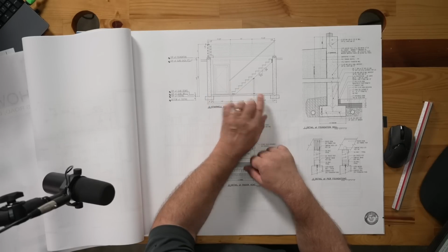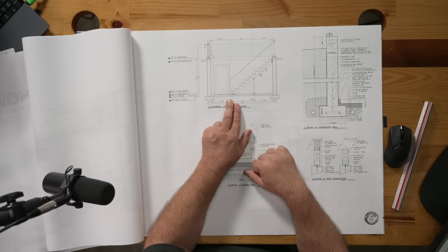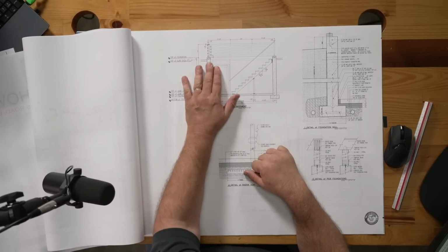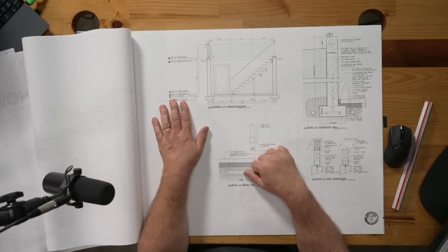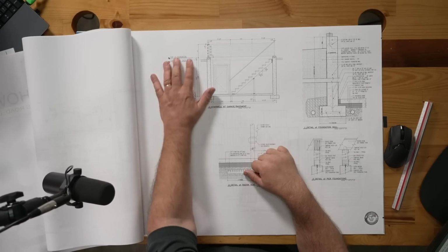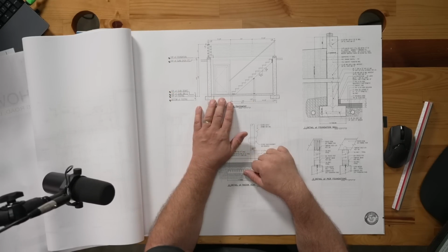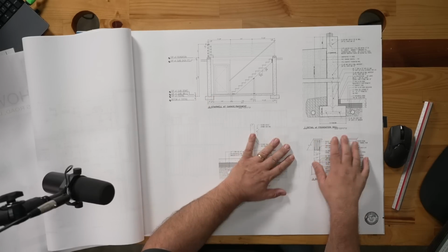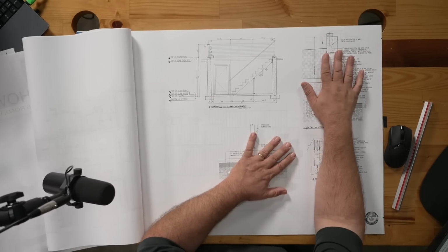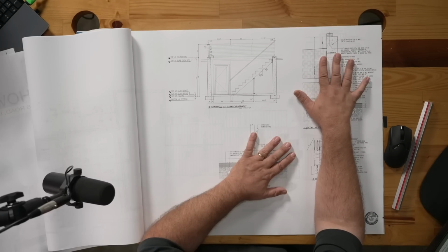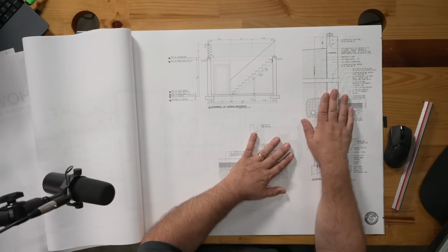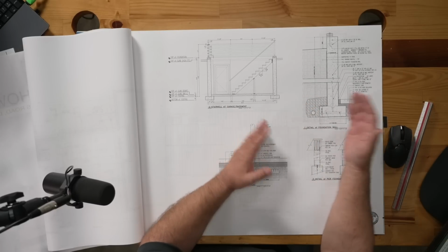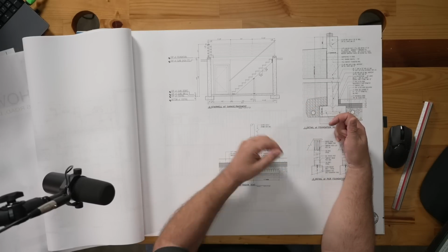Just a really quick section. Here's a section showing that stairway down to the garage and some of the elevations so that the builder knows, hey, what are we talking about? How tall is that? How deep does this go? And then some associated details, some of the pier details. I always typically do a typical foundation wall detail with the foundation plan so that the foundation guy doesn't need to go through and know all about what kind of siding and what does the roof look like.